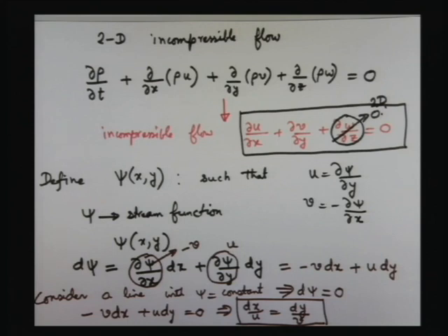But there are subtle distinctions between the applicability of streamline and applicability of stream function. Streamline is defined for all flows. All flows will have streamlines. But all flows will not have stream function defined. Stream function is defined only for two-dimensional incompressible flow. But streamlines are defined for all possible flows. So, this analogy exists only when both streamlines and stream functions are there in the paradigm.